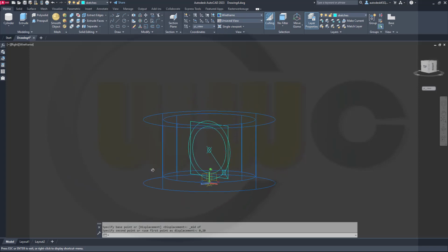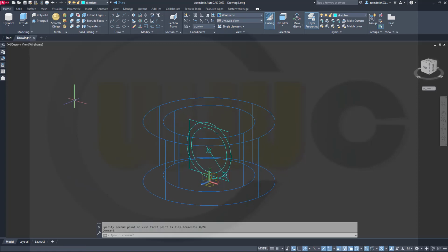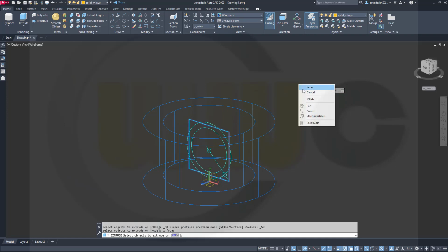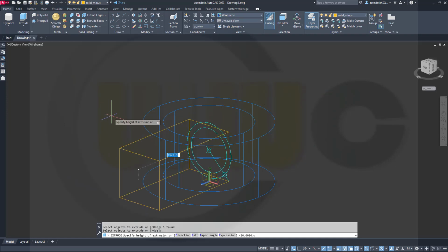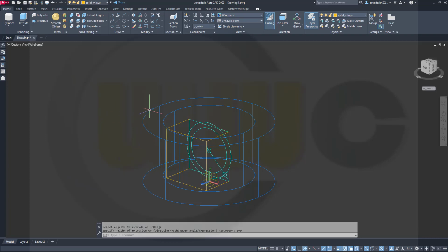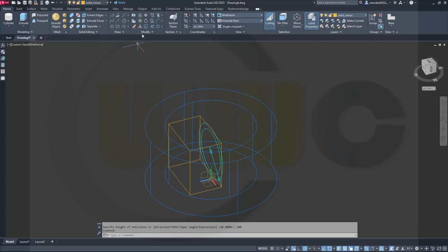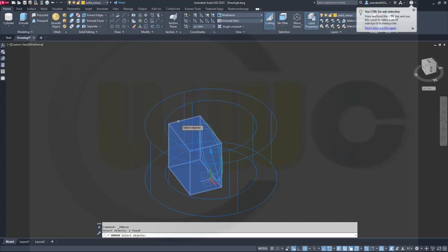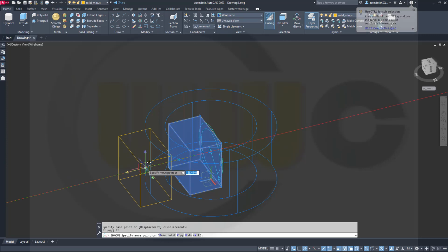And now I can make an extrude, yes, on a different layer. So go for an extrude that square, right click, in that direction, maybe 100. This has to be moved, so go for that 3D move command, right click, go here and move it 171.